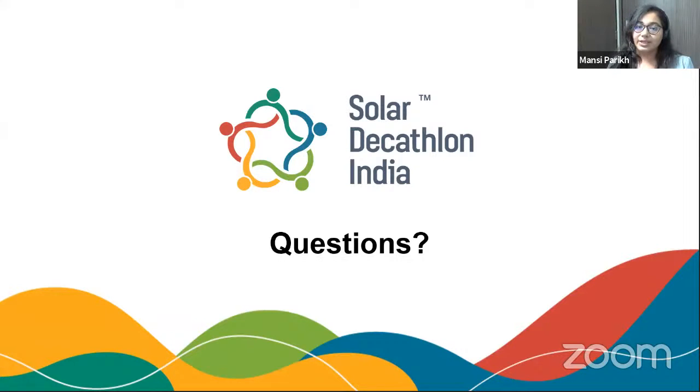Doing multiple U values actually helps us in seeing the curve of the graph. Generally, we see a point of diminishing returns, where beyond a point, say 0.2 or 0.3, the amount of reduction which we get in terms of annual cooling energy or in terms of peak cooling load, which would help us in system sizing, is reducing. So I would say it is good to have a sensitivity analysis.